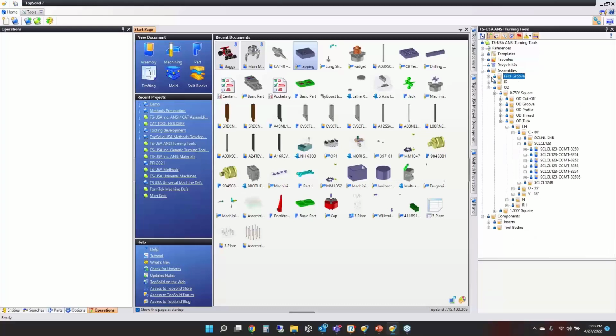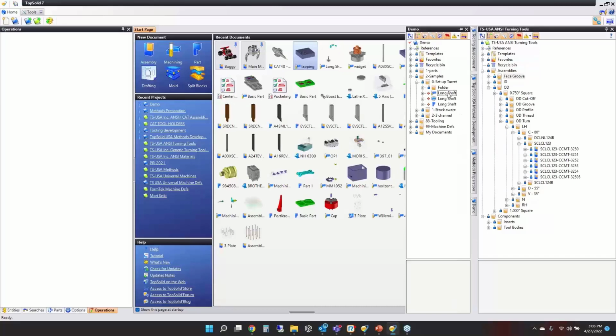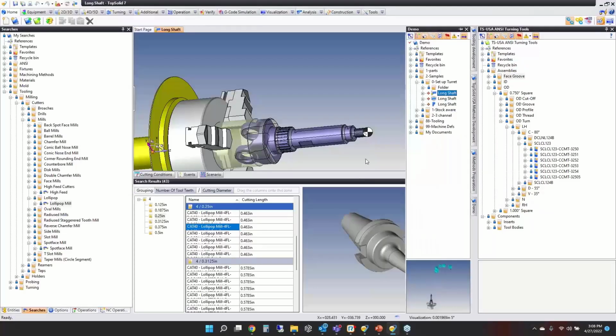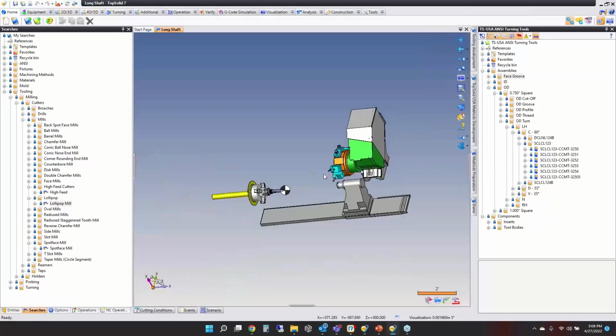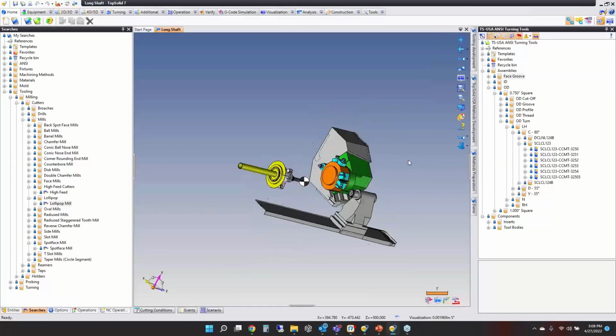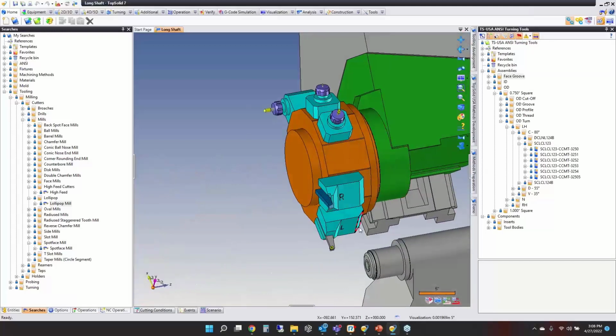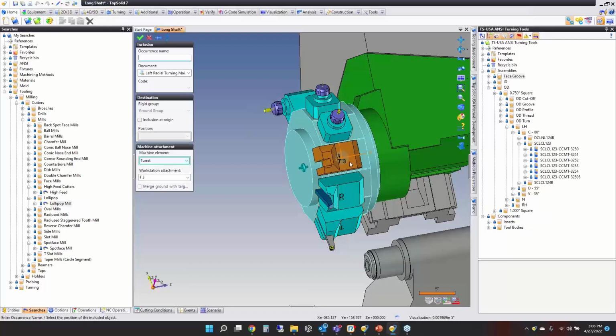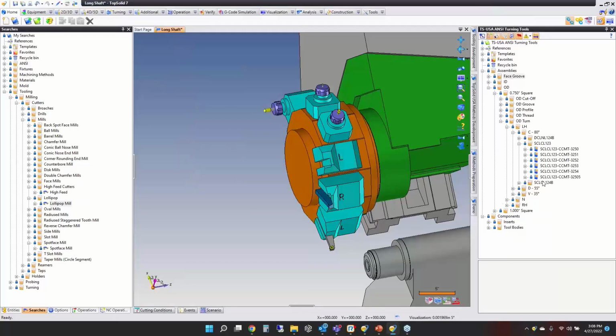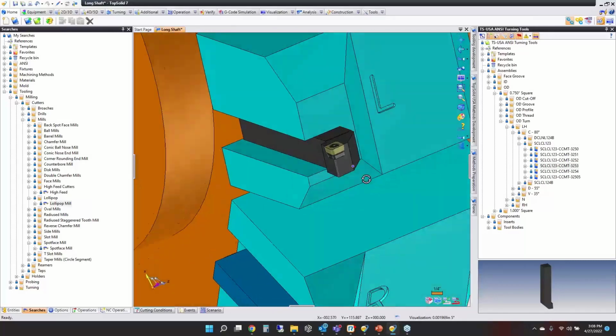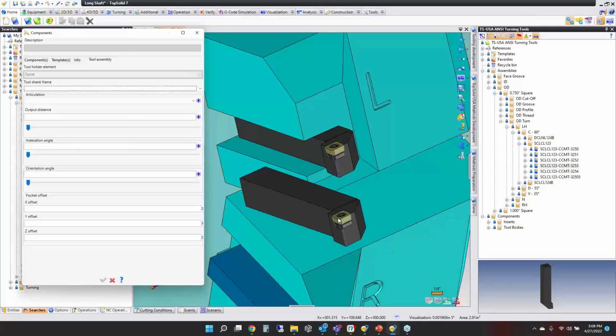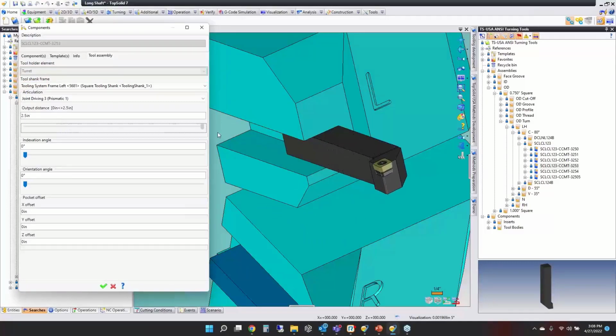Now, let's look at how these can be used. So, for example, I'm going to go ahead and open up a little sample file here. Okay. We can get rid of this one. And here we have just a simple little turret base lathe, right? I want to use this same holder type, so I'm just going to control drag and drop that holder type up to pocket 3. That's perfect. And then I'll take this tool right here, why not? Drag and drop it right into there. And if we go and edit the tool, of course, you can play with its stick out distance.